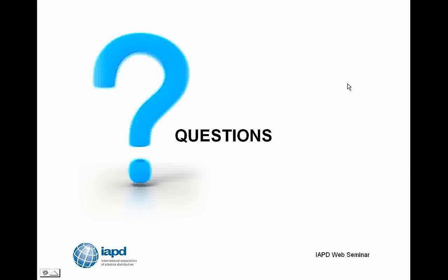To give some general comments on that, I would start to look at any number of materials as possible candidates. One good one is PAI, polyamide imide, which tends to have good high-temperature performance. Another good one is polyimide, PI. And finally, really shifting gears on you, there is a thermoset material called G7, which is a combination of silicone matrix and glass fibers that can start to play around at those types of elevated temperatures. I'm not saying one of those three is the right candidate, but they're decent places to start.